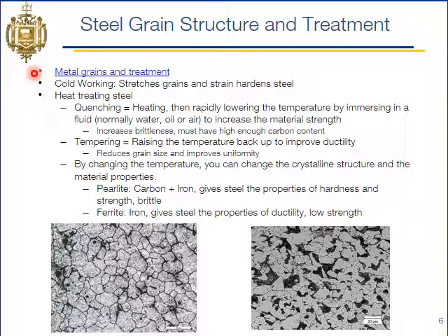All right, welcome back. So hopefully in the video you saw that we can cold work metals, right? That stretches the metals out, usually in some kind of rolling press, and that stretching causes some plastic deformation and strain hardening. Some really good examples of cold worked metal are body panels on your car. They're made by essentially large presses or large rollers. You take a big flat piece of sheet metal and you press it with some type of press or mold, and that bends the metal, permanently deforms it, and strain hardens it,